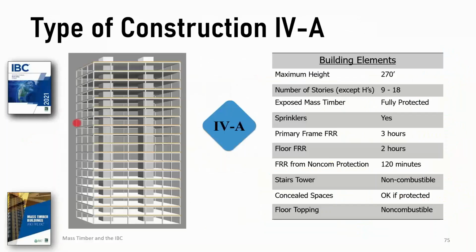They do result in good sized buildings, but keep in mind that there's also a total allowable building area, not just area per story, but building area that kicks in. So as these buildings get taller, they're not unlimited in area. So the area of the total building has to be limited to the area that is represented by the maximum single story area times 3. So as a building gets up to 18 stories, these allowable areas per story get smaller. Keep that in mind.